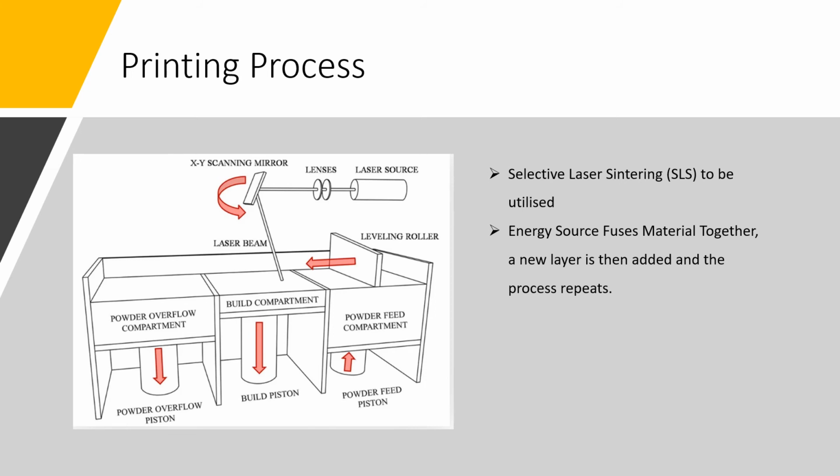The process works in the following way. A thin covering of metal powder is laid on the build platform of the aluminium 3D printer. A laser selectively binds parts of the powder to build a solid layer of the model. The build platform lowers, and the printer uses its recoater to distribute another covering of metallic powder on top of the previous layer's fused and unfused powder. At this point, the process repeats itself layer by layer until a complete model forms. It is crucial to note that the melted powder is cooled quickly to form the metal.